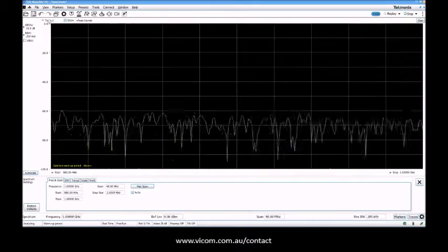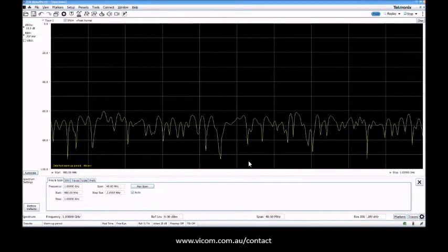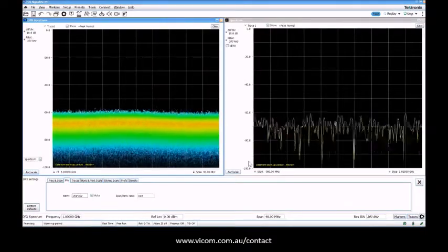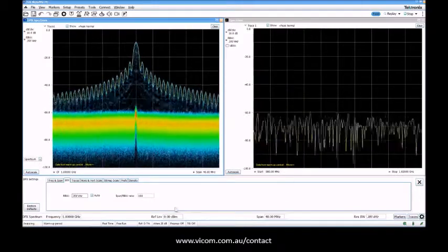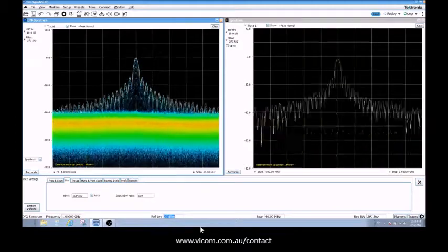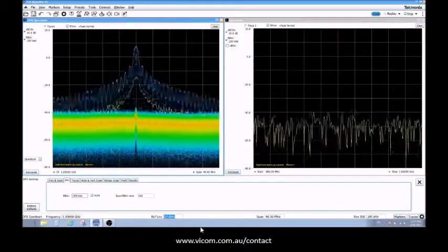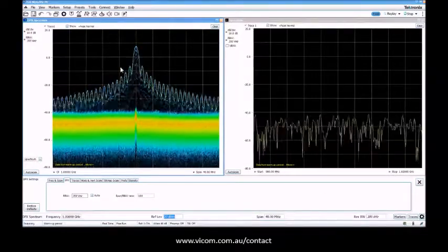I'm just, as usual, running the DPX to see if we have something here, and I'm trying to squeeze out as much power as possible. And you can see here is some signal. First of all, I'm going to put the ref level and tweak as much power as possible out of this baby, which is above 16 dB. This is the maximum I can get out. And here you can see the difference between real time and non-real time.